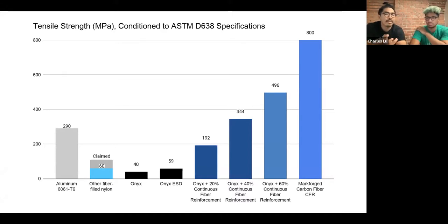Really the standard that you should work to is a conditioned sample, because practically speaking, one, you're not injection molding nylon. No. So that's like a major difference. And then two, atmospheric conditioning is a real thing that happens to a number of thermoplastics. And you want to condition your part in a way that it's absorbed some amount of atmospheric moisture so that it's like an accurate representation of what you're doing.